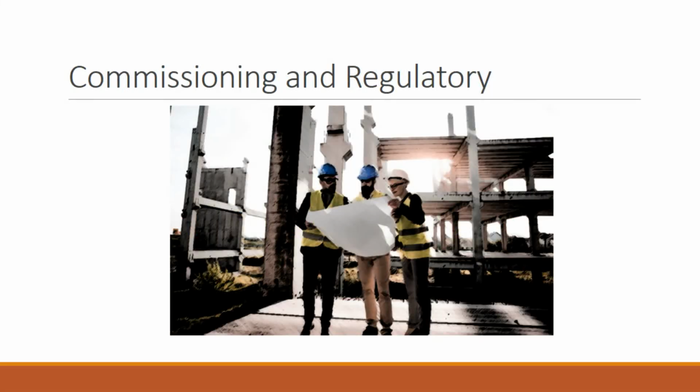Now, before an equipment, facility, or system is put into use, it must first be commissioned. When facilities, systems, and equipment are started up and turned over to end users, commissioning is the well-planned, documented, and managed engineering approach that results in a safe and functional environment that meets established design requirements and stakeholder expectations. Commissioning then reasonably ensures that the next step of verification for regulated industries, such as the utility industry, will be successful by confirming that what was specified was installed and it functions as intended, and that it was successfully turned